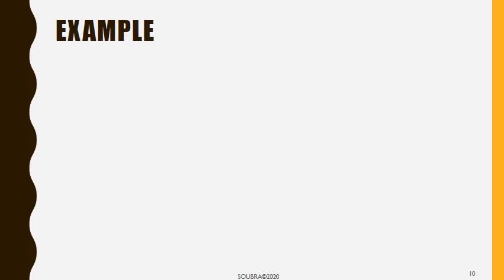Let's see an example that would be easier. So, which port is concerned with this particular instruction? So we can see that we have the name A here, so most probably and definitely it's port A. So I'm dealing first with the DDR register. This register is used to do what? To know whether I'm going to use it as an in or as an out. I'm putting all zeros.